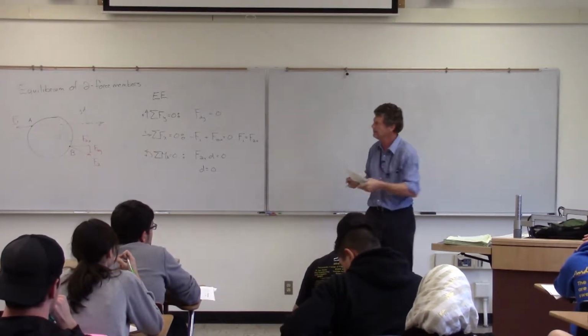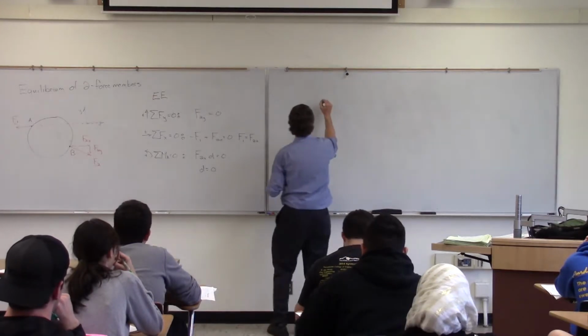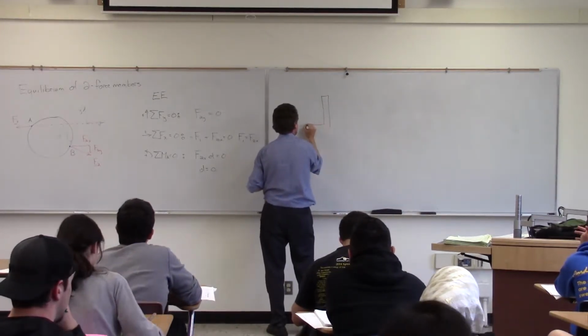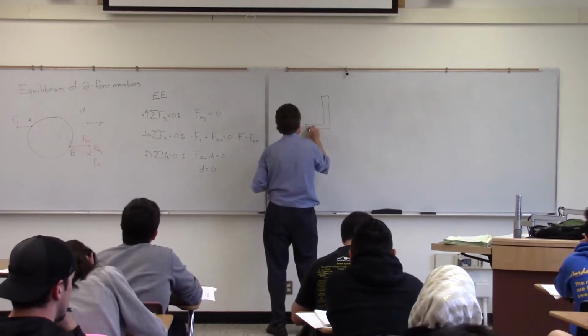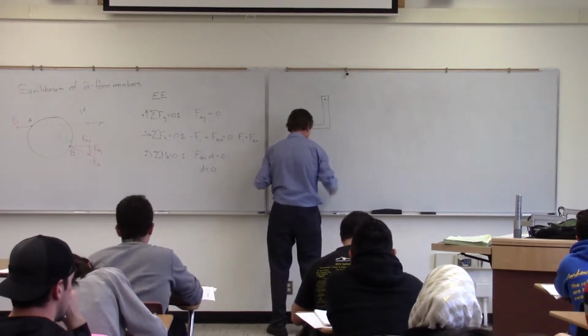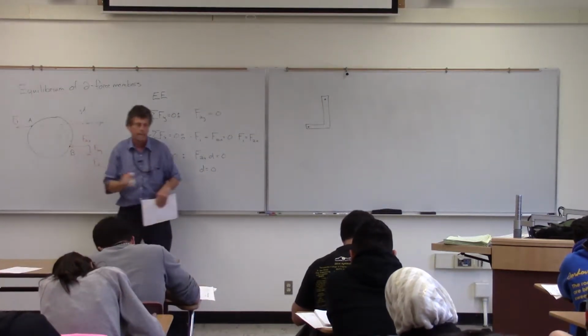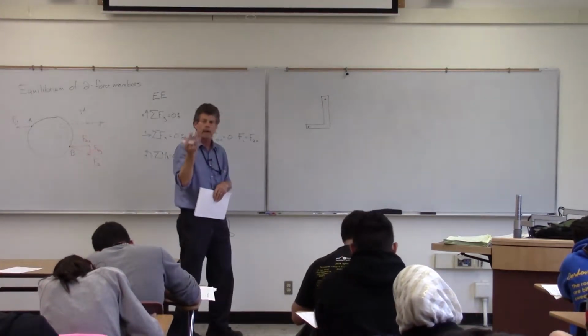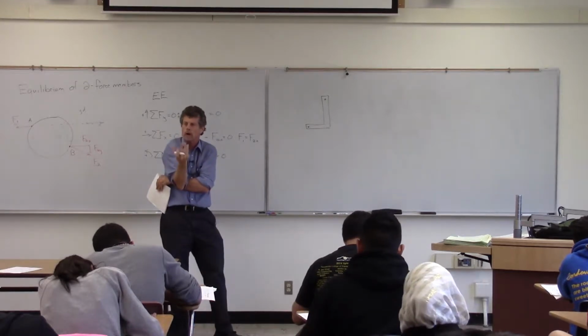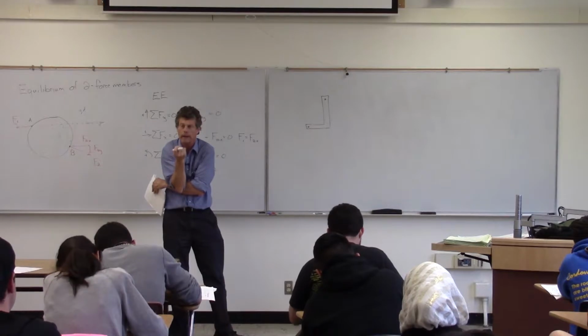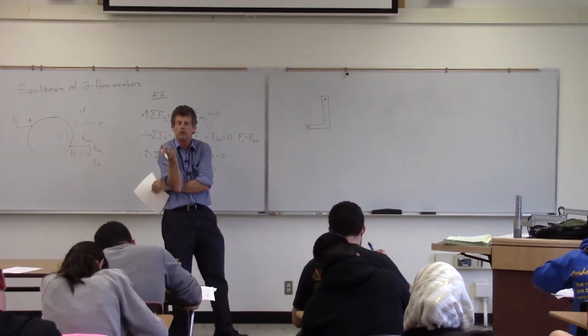So yes. Let's think about a situation where we have an angle that has a couple of pin connections. At a pin connection, recall, if I pull that away, whether it's attached to the ground or attached to another body, a pin connection has two unknowns, right?